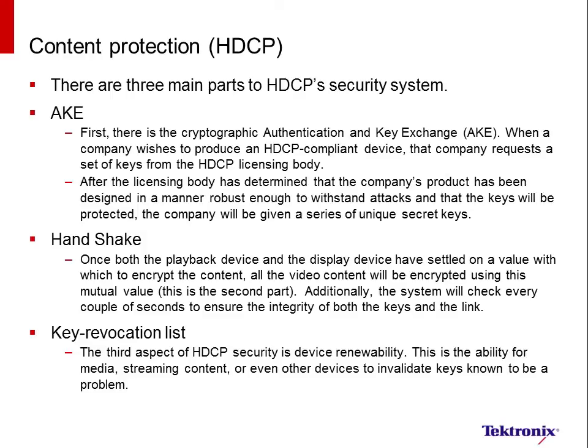The key revocation list is in newer receivers and the newer standard, where if a receiver has been deemed to not play according to the standard, or the body that makes that receiver, the company, they can actually be removed from being able to display HDCP data. So newer receivers or newer transmitters have a list of older devices that have been kicked out of the party and are no longer allowed to decode the video.